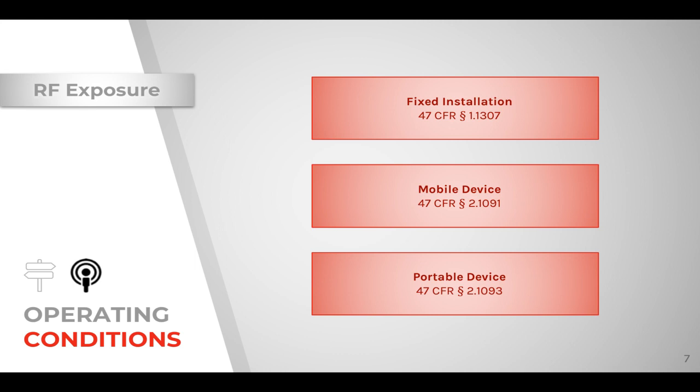This is when we would use SAR measurement if required, or do calculations as per the SAR limits. These products would be used in a near field condition and you'd get more localized exposure. So we would have to see if the product qualifies for SAR exclusion based on the SAR thresholds, or if not, then we need to do SAR measurement and evaluation.